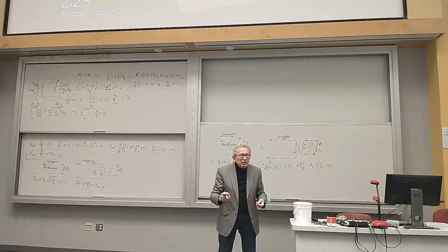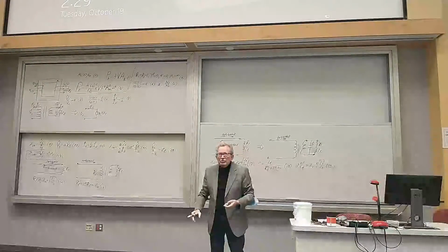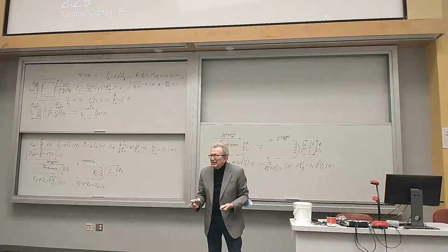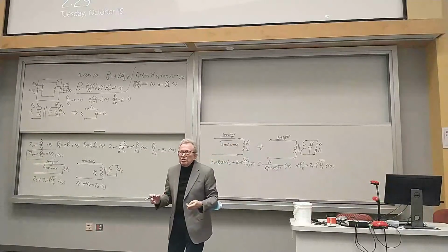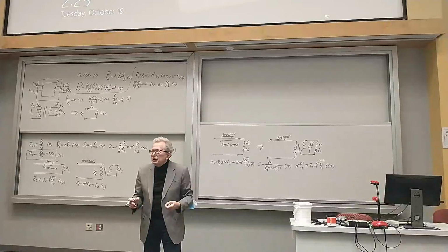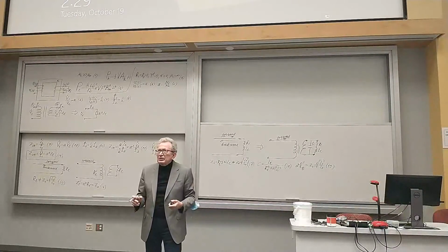Then the same capacitor is used to adjust this total impedance to behave as a resistance with power factor equal to 1. So you see, it's again very useful. When you study power electronics, capacitance will be very useful for suppression of ripples, because power electronic devices are switch mode devices.